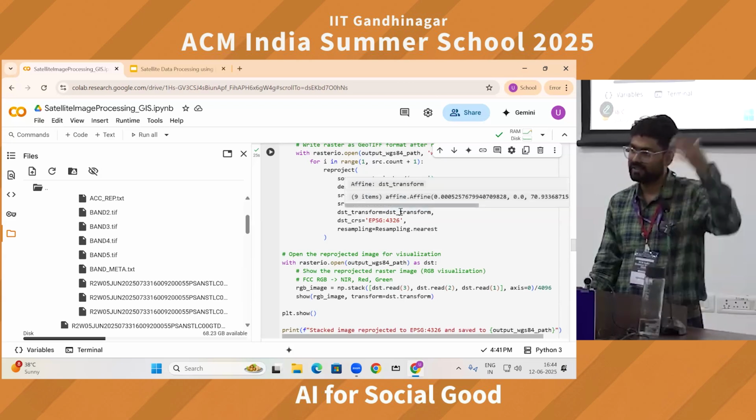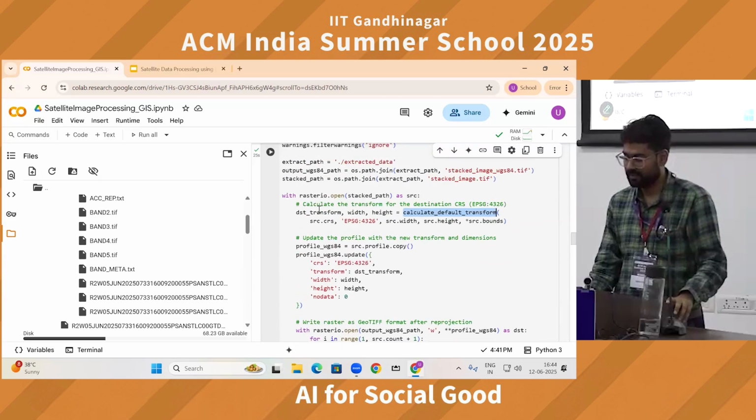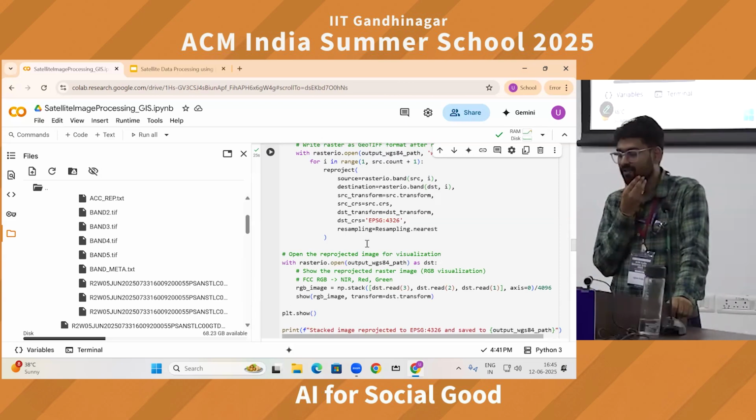Destination transformation that we computed earlier in this line, then destination CRS, then resampling method. By which method you want to do the resampling? By default, in most of the GIS software, it is nearest neighbor.